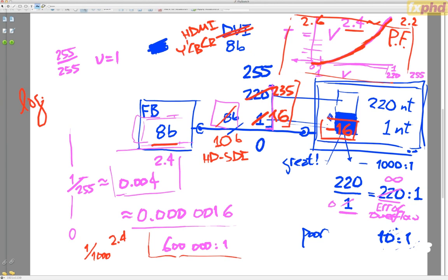Of course, the numbers that I'm referring to here in contrast ratios like 1,000 to 1, 200 to 1, 10 to 1, these are the numbers that you actually measure with a color measuring device. And the numbers that they put on the box or on the spec sheet, they're completely different. Like Sony might say a consumer OLED does 1,000,000 to 1 contrast ratio. Well, these numbers just can't be believed. They're not measured in any sort of reasonable way. Okay, so there we go. That was a longer explanation than I had hoped, but a really important one.